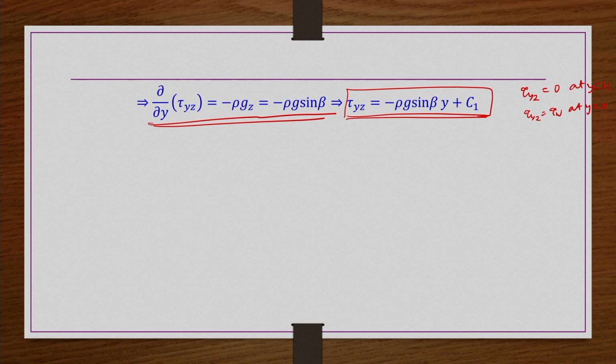So at the inclined surface we are going to have the maximum wall shear stress, and the material is flowing down in this region. The upper layer of the fluid is open to the atmosphere, so y = h is going to have 0 shear stress. So that is the boundary condition we apply: at y = h, tau yz = 0.